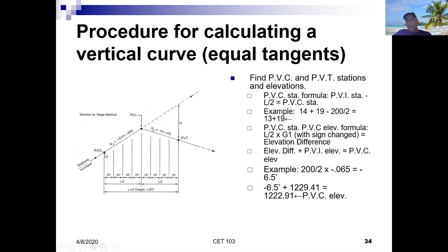And that would be the elevation at which this point is going to climb every 25 feet. I would then calculate the elevations along the vertical curve, or the vertical line, this first G1 grade going in. I would calculate elevations at each of those points as we went through, all the way till I got to this last point right here.